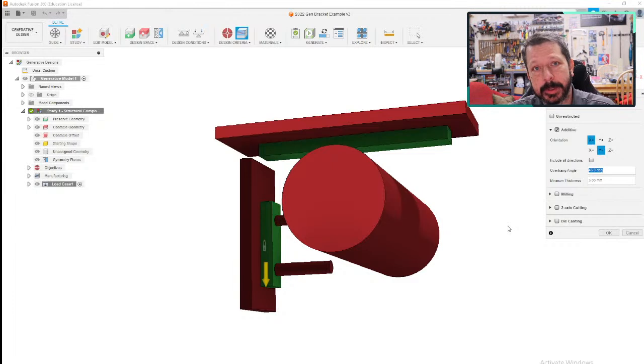And so it can help with creating a part that not only is optimized for lightweight and rigidity, but is printable without supports, which might also be another factor you're considering. You can tell it a minimum thickness so that it never gets any really thin parts, because most printing processes at some point are going to break down when you try to print too thin.